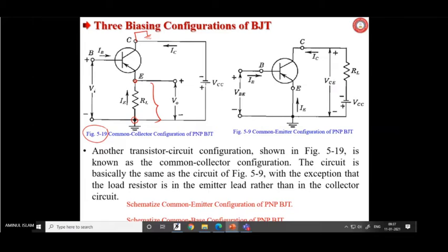Yes, sir. So now you are not asking why the DC source has to be grounded for AC analysis. Why you are not asking that? I said that DC sources have to be grounded. All the DC source voltage, if it is a voltage source, has to be shorted to ground. If it is a current source, it has to be opened.